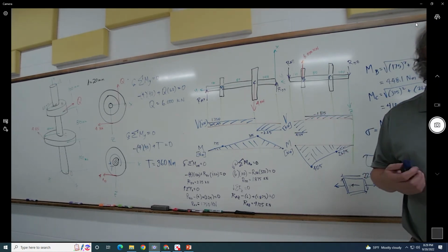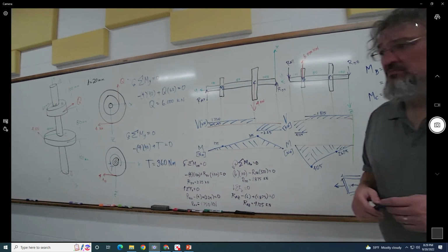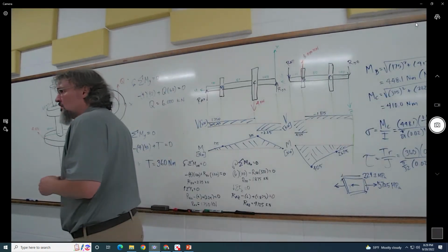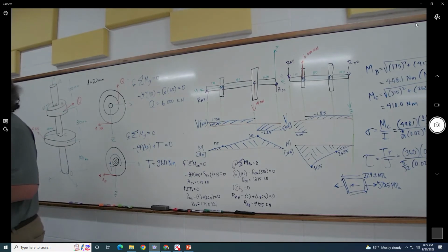And to work on more problems along those lines. And tau is just that. Tau is not transverse. No, it's only torsional shear. That's torsional. Just torsional. And like I said, the transverse is going to be relatively small compared to the torque, the torsional shear. Most things will break in torsion.